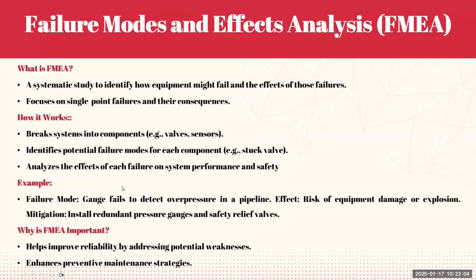Then we have the failure modes and effects analysis, which is the FMEA. FMEA is a systematic study to identify how equipment might fail and the effects of those failures. This one focuses on single point failures and their consequences. How it works is it breaks the systems into components, let's say valves, sensors, and so on.